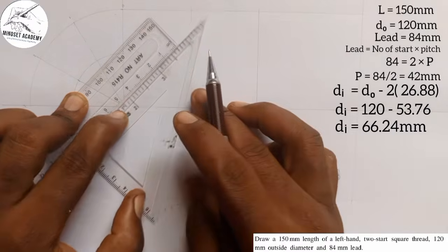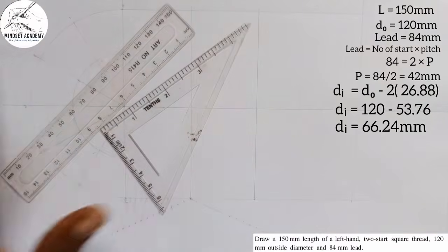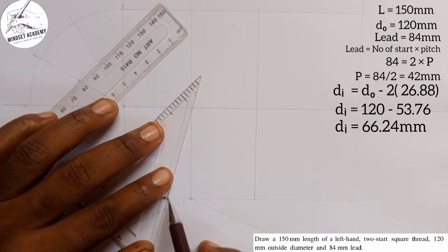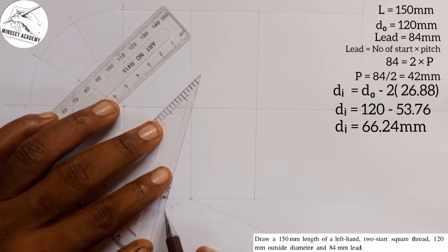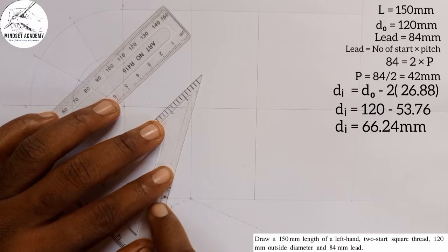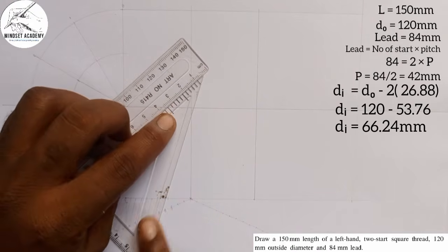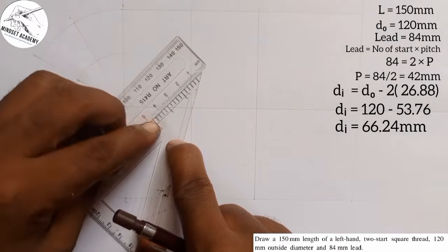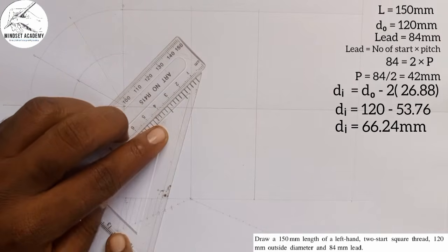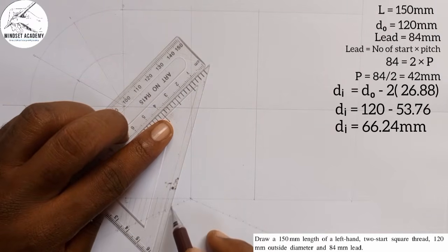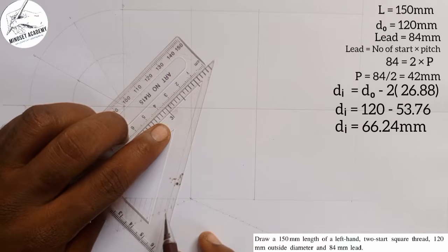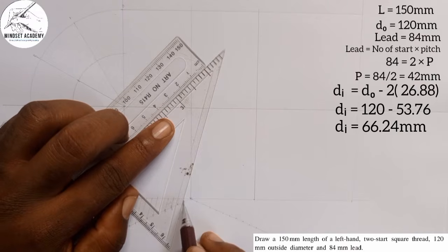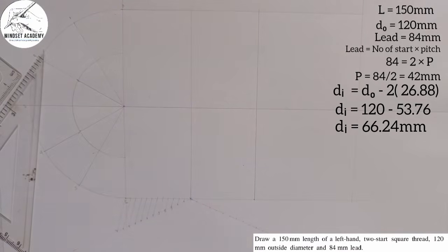So you can really readjust it again. If it scatters, you ensure that it is meeting here at this point. They are on the same line with this line. You can see that. Then I'll move this to here. Same line. Then I'll take my ruler and place it at the base again. Then I'll move. I have this. I'll move. I have this. And I have this. So I'll divide this into 12.